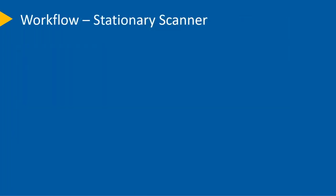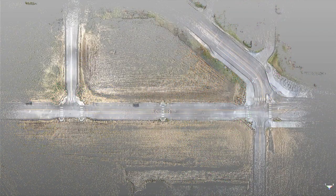Now, if we look at the workflow for a stationary laser scanner, you'll put the scanner in one position and do a 360 scan. It'll scan everything in sight, basically, except for right underneath the tripod in most cases. Then you'll move to the next position, and then the next position, and you'll continue scanning all of the positions that you need to see in 3D all of the data you need to complete your project. This all registers, or comes together, to connect these in one final cohesive point cloud. We'll talk a little bit more about registration and putting these scans together later.